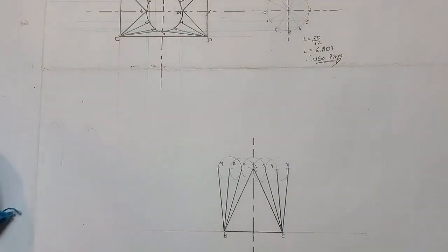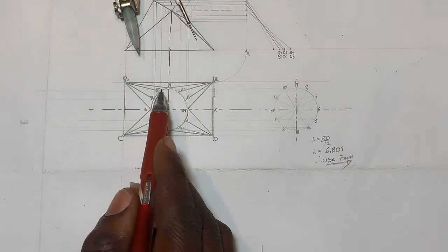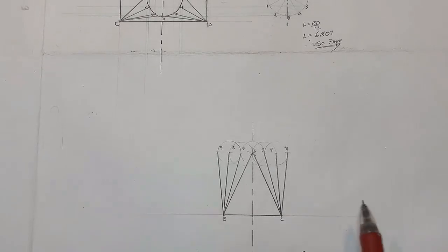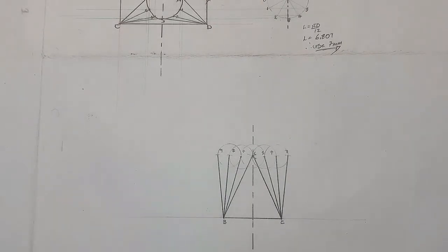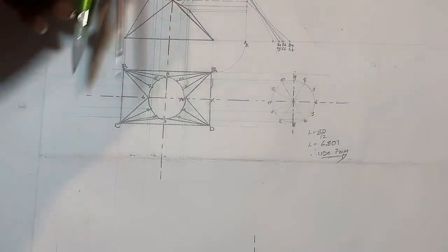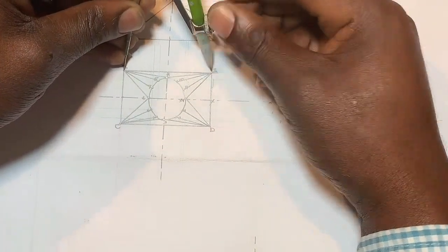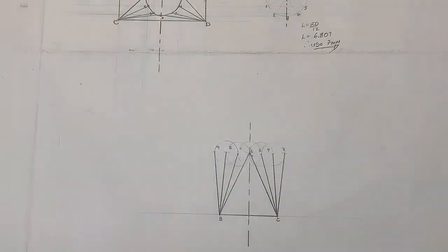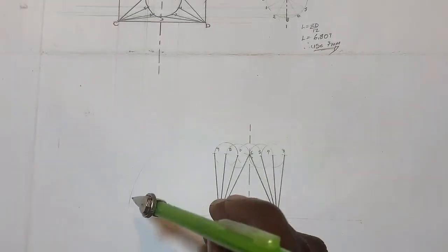Simple, straightforward. Okay. Now come back to your top view again. You see what is going to happen now. We have to move from B to A, and B to A is the same as C to D. Understand? So which means this side we have to get D. This side we have to get A. How? By placing a drawing compass at B to A, which is this one. There it is. Then from there, come to your development, place it at B, strike an arc this side, just make it a little bit long.